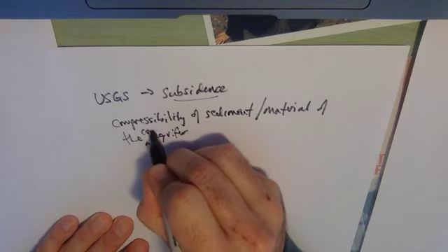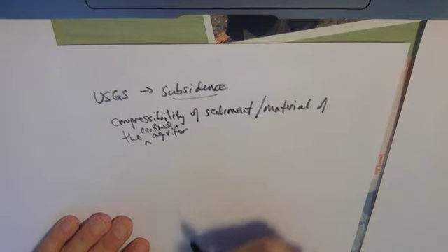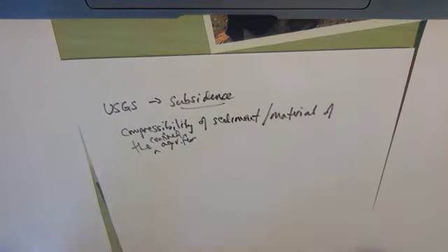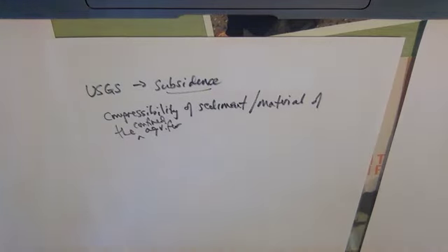The confined aquifer. You really don't get this kind of effect in an unconfined aquifer because the water is just sort of filling in randomly wherever there's an open space, but the water's not bearing any of the weight of the overlying rock. It's only because the water is trapped in the confined aquifer that it bears the overlying weight.